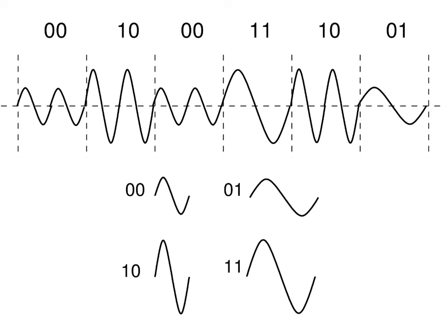Given the same conditions as before, our T equals 2 milliseconds, that is, this period is 2 milliseconds. What's our signaling rate? This is one signal element. If this is 2 milliseconds and one signal element, we have the same signaling rate of 500 per second.